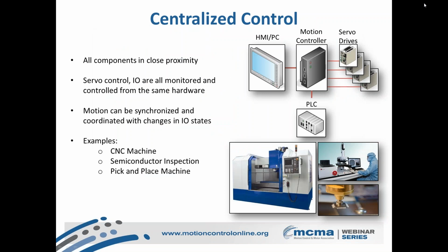So now we'll go into two of the main control system layouts, one being centralized, the other distributed control schemes. In centralized control, typically analog control signals are still predominantly used. The operative word with centralized control is coordinated, specifically coordinated motion, coupled motion, these kinds of terms. I'll probably be saying it many times.